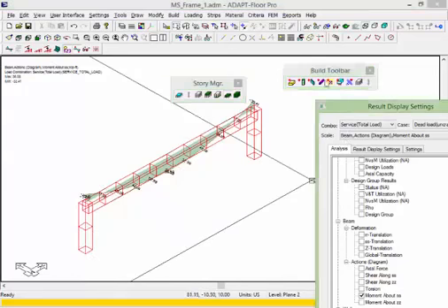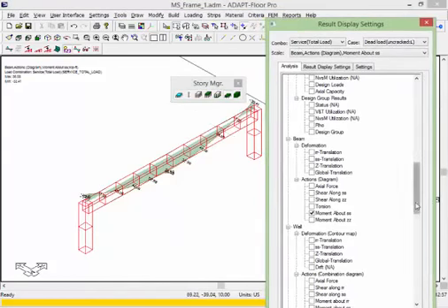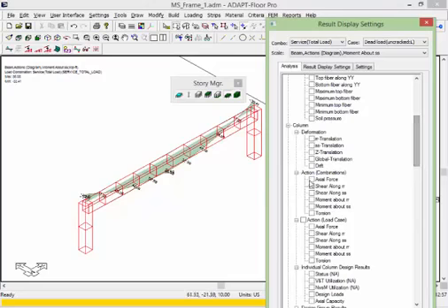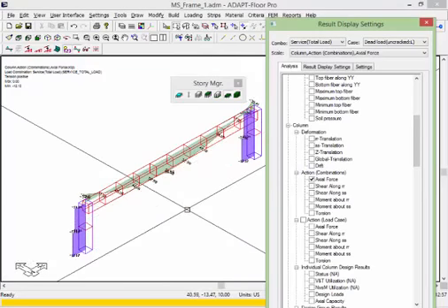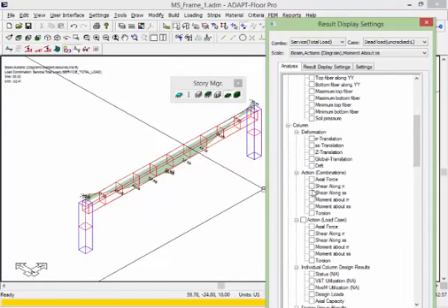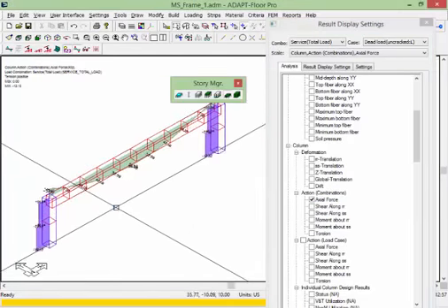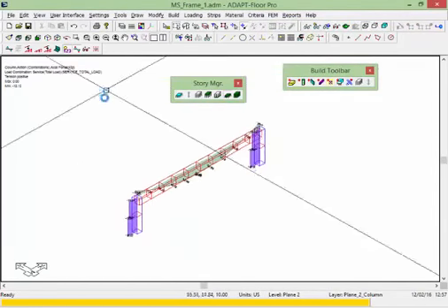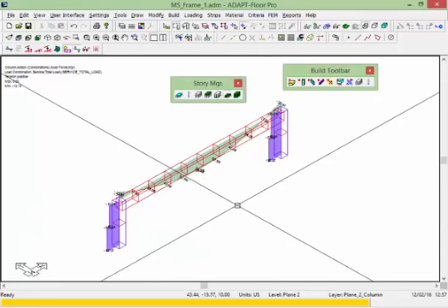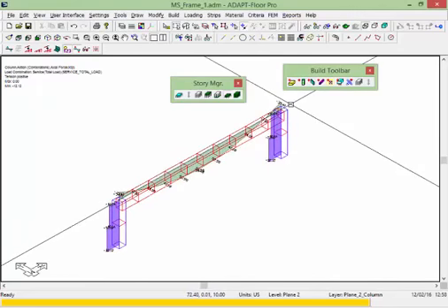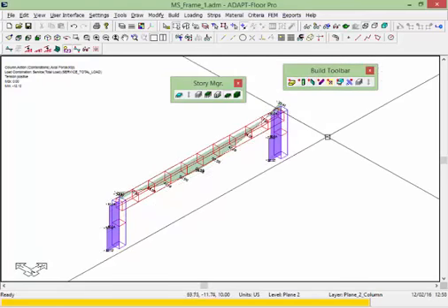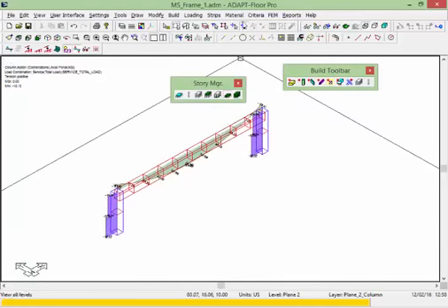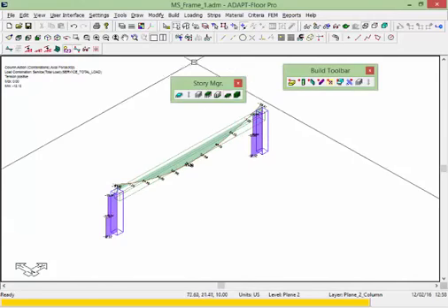And if we go to column, for example, I go over here to column, and here in the column I can look at axial forces for columns, I can look at the shears, moments, and so on for this particular frame. Like any other model, we can add loads to the frame so long as the loads are along the longitudinal center line of the beam element. So we're going to go ahead and turn off these results.